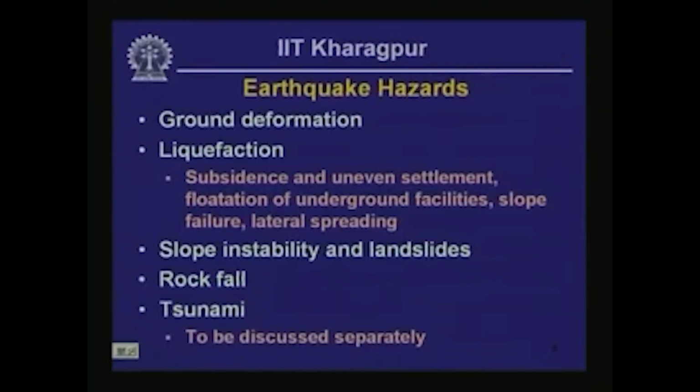So, the buoyant force is also twice as high, and if the fact that the surrounding soil may liquefy was not considered in the original design, then the underground water tank may actually float to the ground surface.